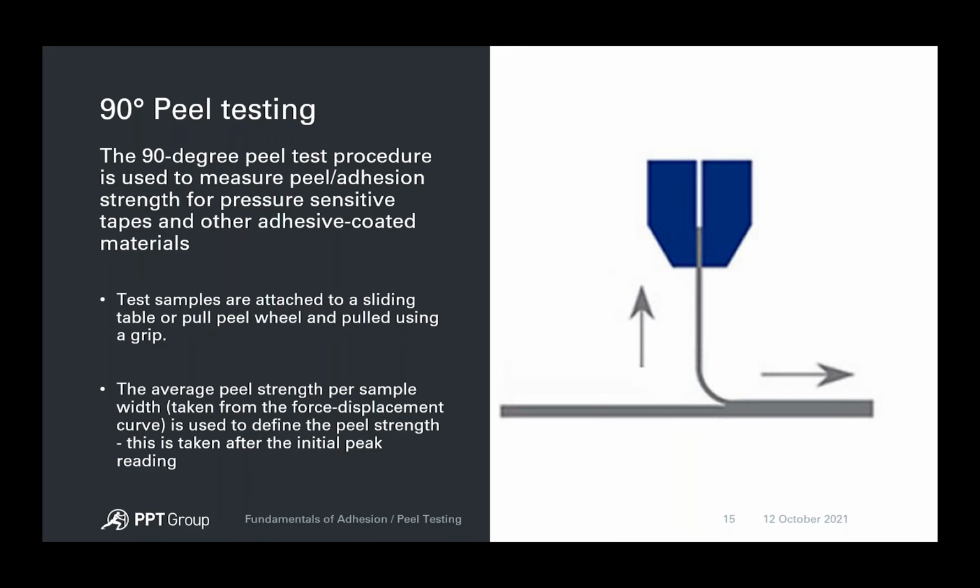And one of the 2 glued components should be flexible enough to be bent 90 degrees without breaking. As for the test setup, the test specimen is clamped on a free-moving table. From one end of the specimen, mechanically debond or separate the 2 components, usually a distance of about 40 millimeters. The separated top component is clamped in a moving vise, which is attached to the crosshead on the tester.